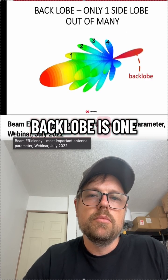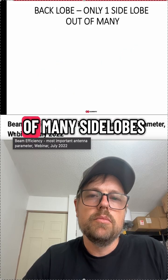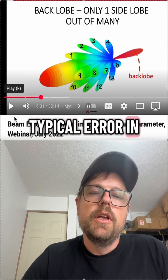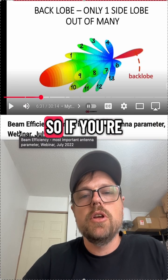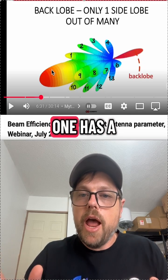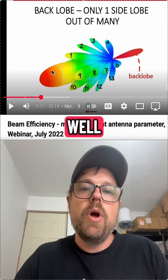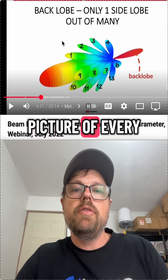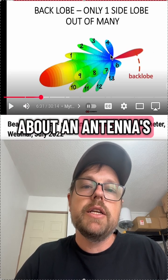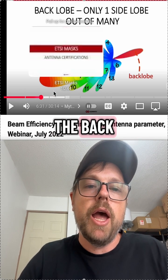Nevertheless, the back lobe is one of many side lobes that antennas used in the WISP industry typically have. So if the back lobe is one out of many side lobes, then it's probably not so important. But it is important for comparison purposes. If you're trying to compare two antennas, one with a good front to back ratio and one with a bad front to back ratio, you can tell about the quality of an antenna based on the front to back ratio. While it doesn't give you a complete picture of every antenna in regards to side lobes, it gives you a good indication about an antenna's ability to focus energy in one direction relative to the amount of energy that leaks out the back.